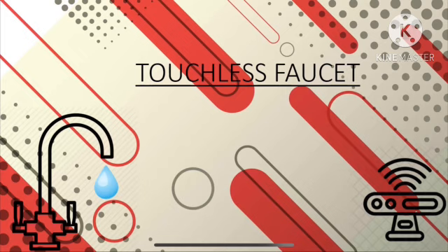We will discuss signal conditioning in touchless faucets. Infrared transducers in touchless faucets confront a number of obstacles that require appropriate signal processing to enable precise and dependable performance. One of the key concerns is ambient light interference, which occurs when external light sources such as sunlight or artificial lighting affect the sensor signal, resulting in erroneous detection.